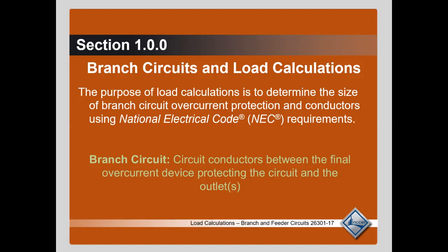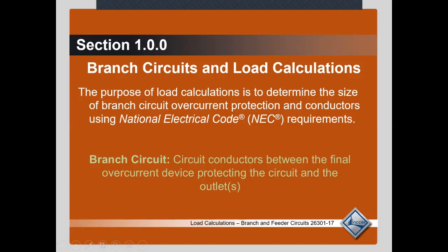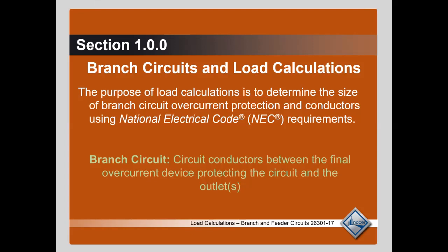even though a 12 wire is, if you go to 310.15(B)(16), it's going to tell you that that number 12 gauge wire. So let's look in there, 310.15(B)(16), and let's see exactly what is the maximum amperage for that. Let's see right here. So it says right here in the table, 310.15(B)(16), that a number 12 gauge wire based off of 90 degrees Celsius, we're going to say it's THHN, is rated up to 30 amps of power.